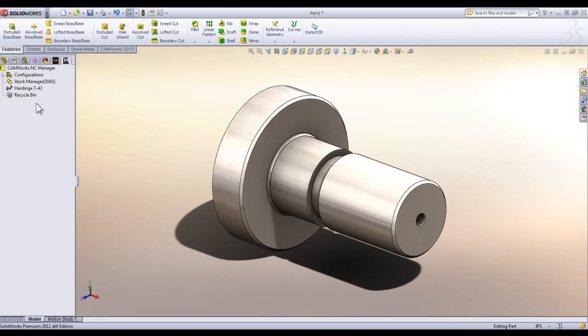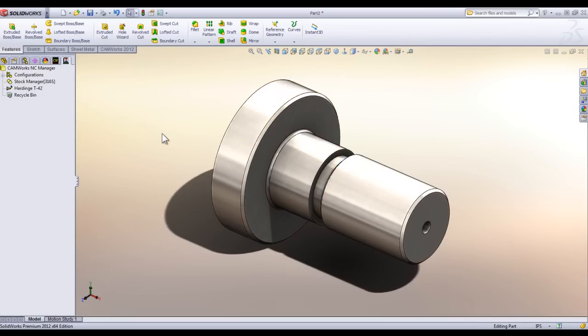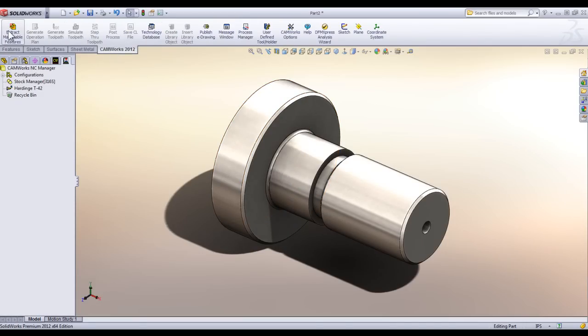And now we're actually ready to start applying some toolpath. Now there are different ways we can do stuff inside CAMWorks. We like to use extract machinable features. If you're already familiar with SOLIDWORKS, you maybe know FeatureWorks, that when you import a model you can use that. And that is actually done by geometric. So we can use that to extract the machinable features.